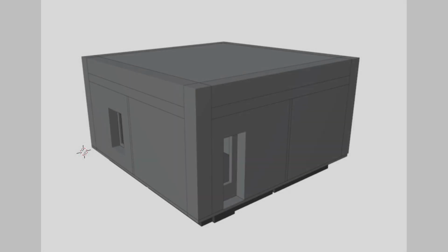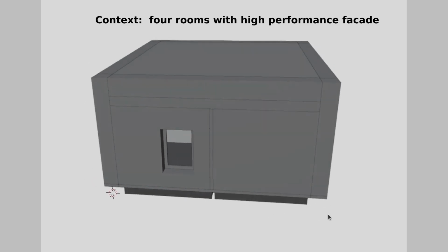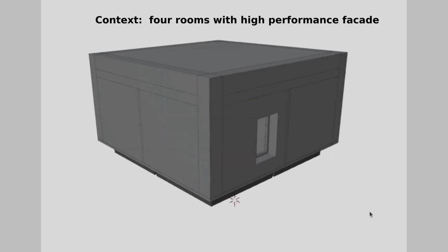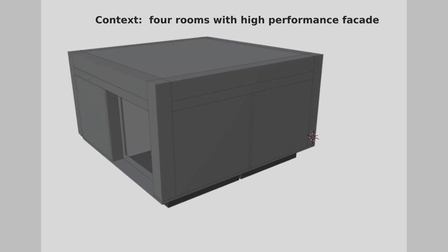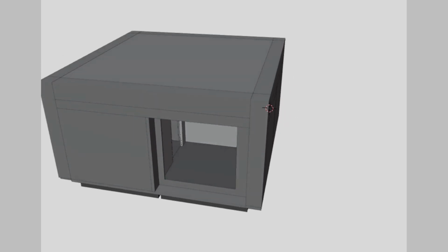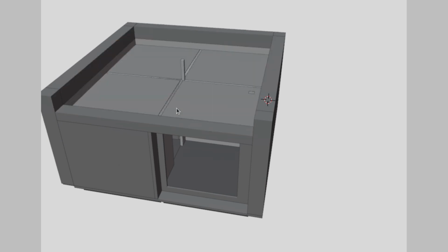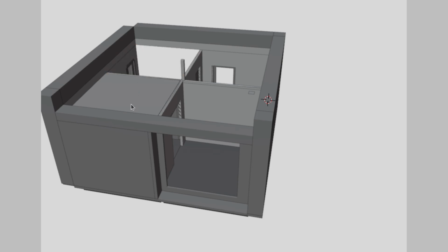The context of this video is also a single-level, 4-room building. The building composition roughly follows the requirements of passive house, so the building sections are seriously thick and thermal bridges are constrained. There is a diversified schedule of occupants, lighting, and small power loads, and there is a simple environmental control that maintains a 20 to 24 degrees C environment during office hours, otherwise free-floating.